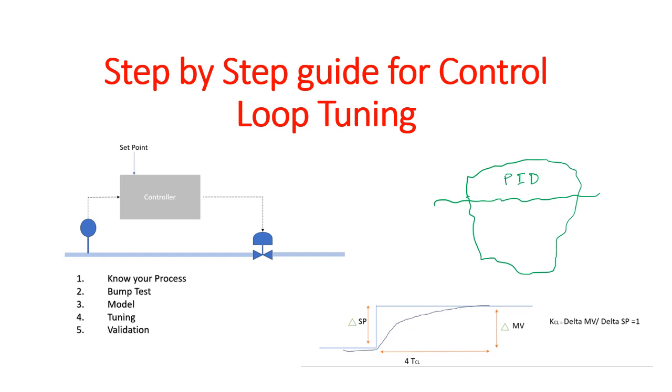You need to know your process. You need to know the condition of the instrumentation system. You need to know what kind of instrumentation, whether it is pneumatic or electronic, whether the process is self-regulating type or integrating type. All these things you need to know to do a proper loop tuning.